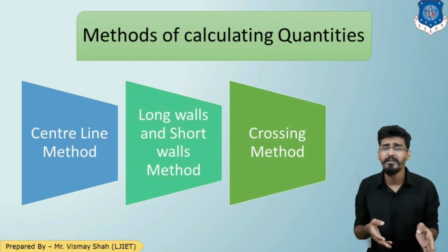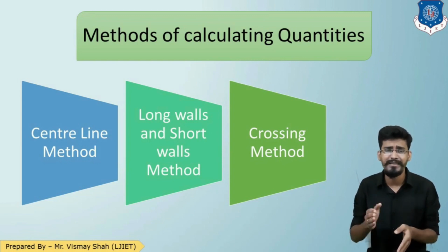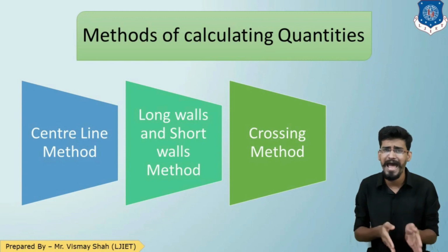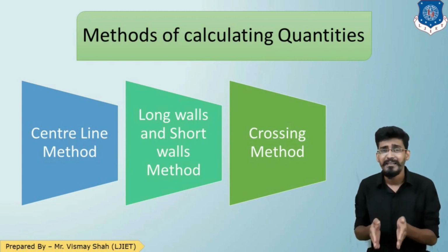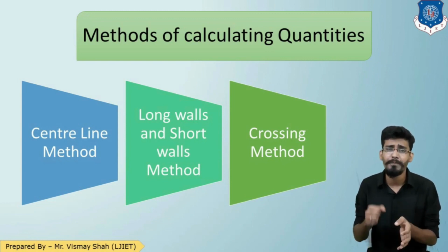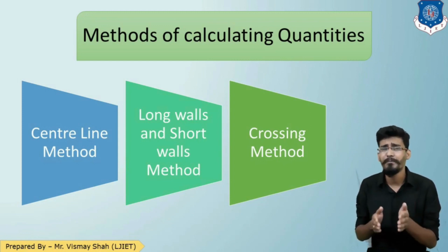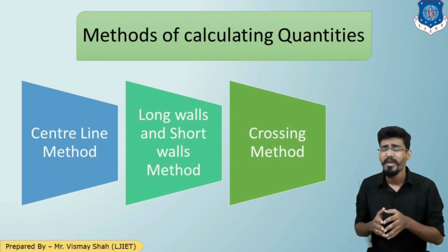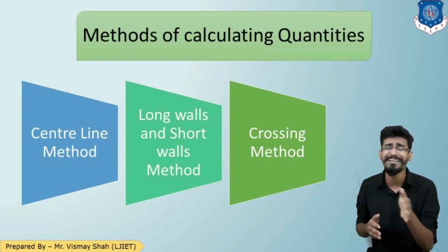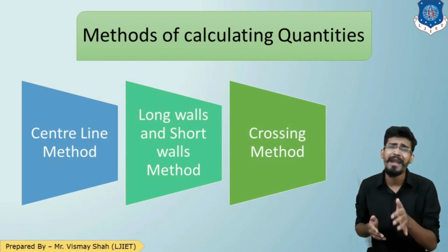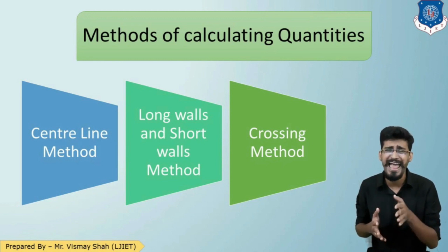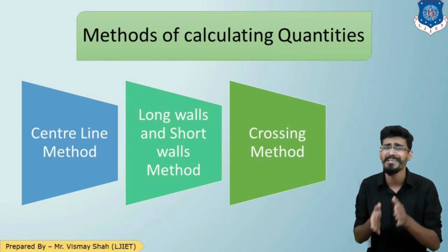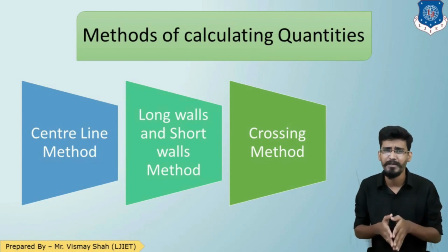Once you divide the entire structure into components, the dimensions are worked out from plan, elevation, and section. Then when you get the dimensions, you prepare a measurement sheet. Then we saw the format of the measurement sheet. Once the measurement sheet is prepared, you have to prepare the abstract sheet. Now what was the abstract sheet? In it you multiply your quantities with the rates, and you add 3 to 5% as contingencies and 1.5 to 2% as work charge establishment.